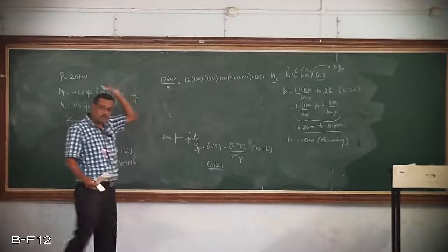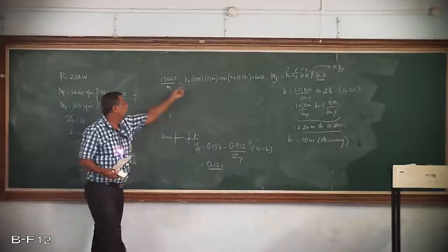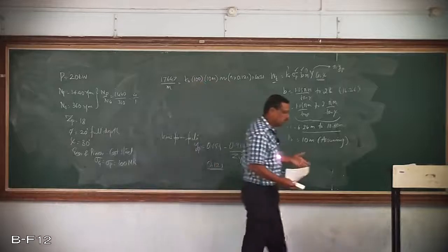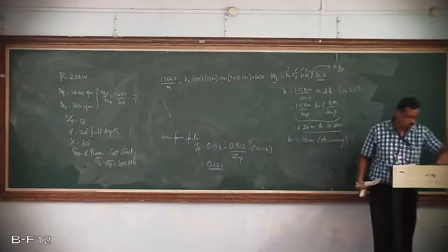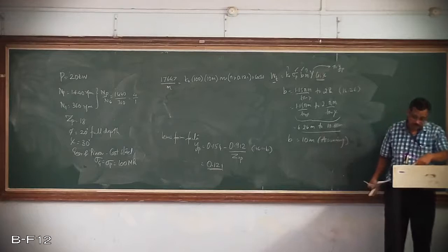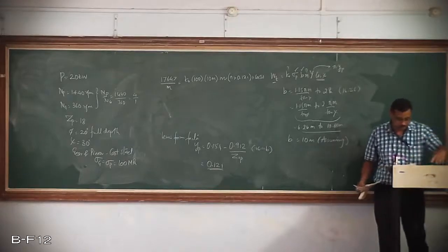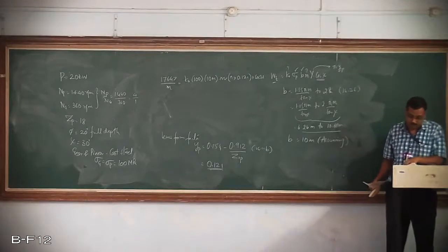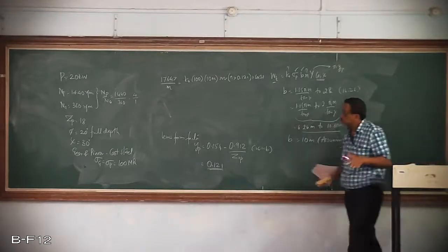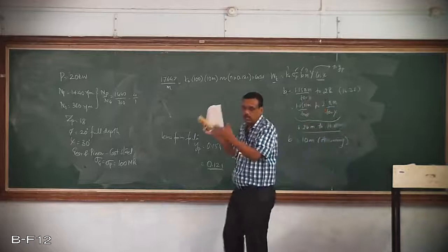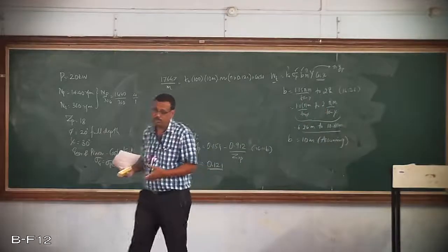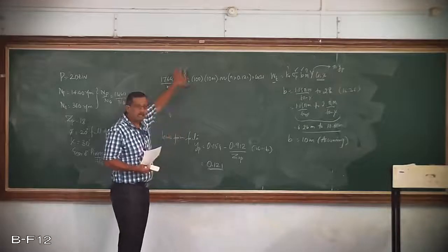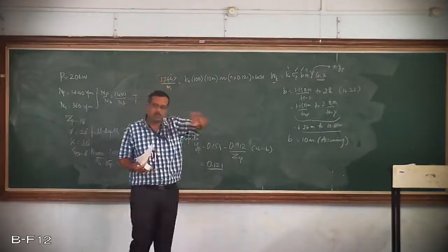So there are two ways of solving the given problem. One thing is you can assume the value of kV. The values of kV have been stated for the helical gear. If you refer to all those equations from 16.3 to 16.36, 16.36 is for non-metallic gears. After 16.35, you can assume the value of kV and go ahead with it, and then check for the strength of the gear for what you have designed. The second is, I'll keep kV as unknown and I'll go with the second method.